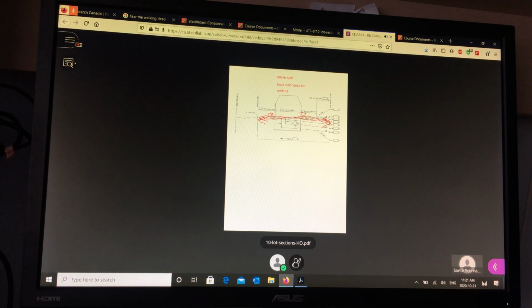When the back split is extreme, when the elevation at the back is so low that you can actually step down onto the ground from the basement, then you have what's called a walkout. And that's the most extreme case. A walkout is you walk into the front of the building on the main floor, you go down some interior steps, and you walk out to the backyard. You walk into the backyard out of the basement, 1, maybe 2 steps down to the ground. That's what we call a walkout. It's the limit of a back split. You can't go any lower than that. You don't want to go down a flight of stairs from your basement.